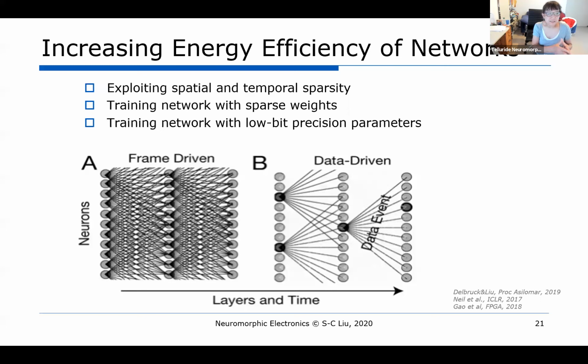And so these networks have become very interesting because instead of just updating all the neurons all the time, and fetching the weights from memory when you need to update the next layer, you can now think of using neuromorphic ideas, thinking of spiking networks where you do it in a data-driven manner, where you find conditions where certain neurons only need to update the neurons in the upper layer, right? And so with this, you can reduce the cost in fetching the weights from memory.